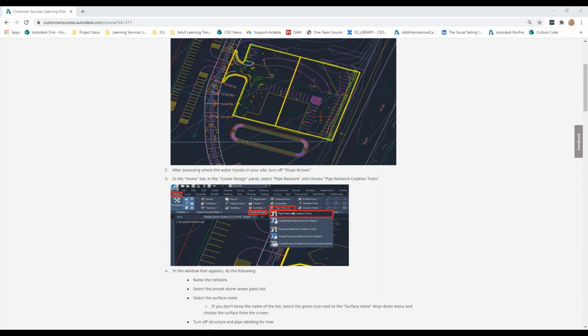And then obviously the front of the curb, or where the curb catches the building, depending on how far away that sidewalk is from the building. But I'd catch front of walk, back of walk, top back of curb, flow line, and edge of asphalt. So those are the key things that you would collect. And then from that, it gives you all of those break lines for the surface that you might need, so that it can create a good triangulation of those points and create a good surface.